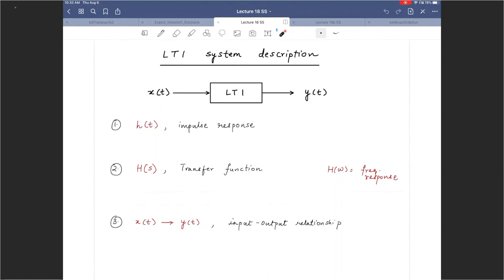And you can use that impulse response to perform convolution, to determine the output of that system for any new arbitrary input. You can do a lot of useful things with the impulse response. So that was one way to characterize this LTI system. For this one, how did we use it? We said y of t, the output, is obtained by taking the input, and once you have the impulse response, you can convolve it with x of t to find the output.